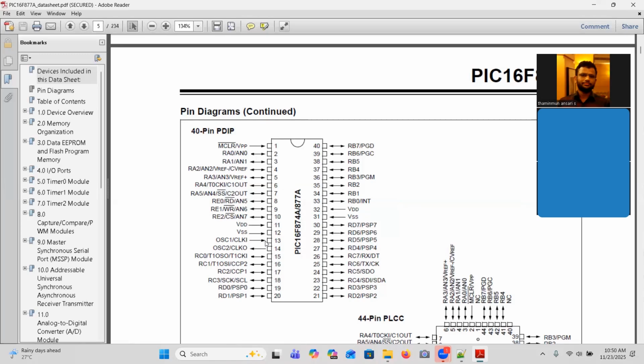Okay. You understood now? Yes, sir. The clock generation can be done through the microcontroller's internal circuit. If you generate it outside, you will simply supply that to pin 30. That's it. The microcontroller will take that as an operating clock and perform every instruction using that as a baseline. Okay, so if we are using a clock, what is the use case of this crystal oscillator, sir?